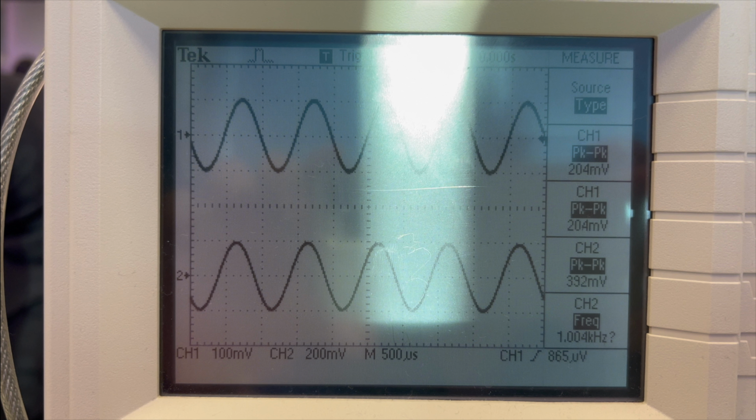Secondly, the function generator is set to a sine wave at 1 kHz with 200 mV peak to peak. By connecting the channel 1 probe to test point 1, the output voltage is somewhat above 200 mV peak to peak, and by placing the channel 2 probe at test point 2, the output voltage I got was somewhere around 400 mV, as shown in the following clip.